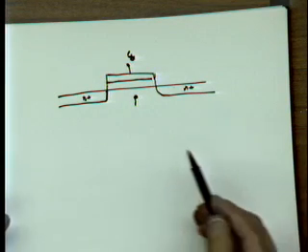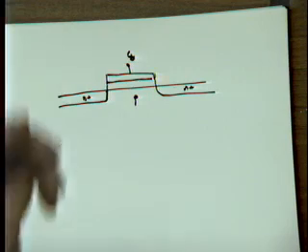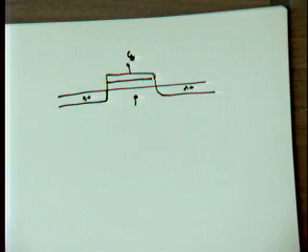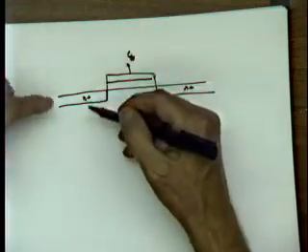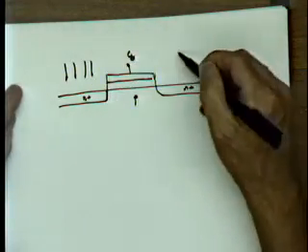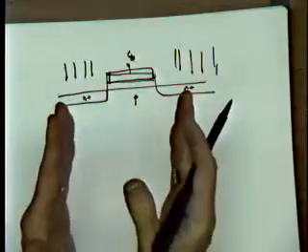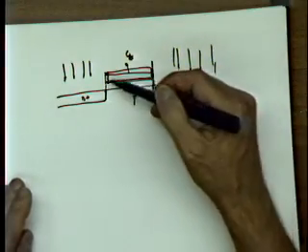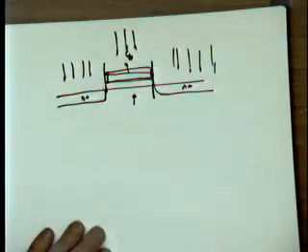What's happening while we're processing the chip, while we put the chip through some high temperature steps, we put it in the oven, at about 600, 700 degrees Fahrenheit or Celsius. Every time you heat up material, diffusion happens. Right? So even though I might create a perfect implant, the way you create the source and the drain is implanting impurities, and you use the gate as the blocking material. So this is why we get perfect N plus here, and we don't get N plus here at all, because the gate basically captures all those particles that I'm shooting at it. So it only ends up here.